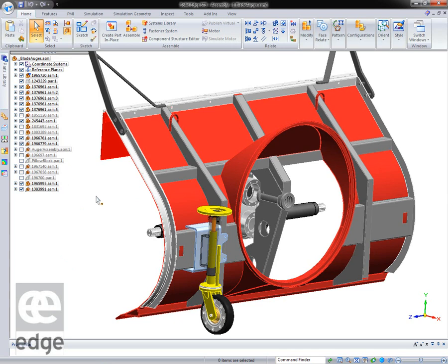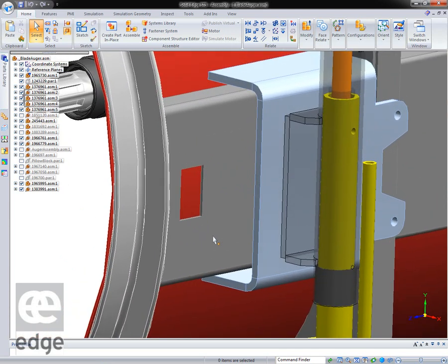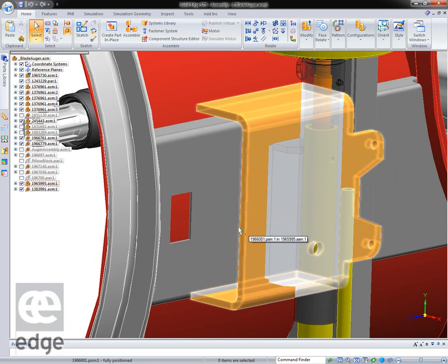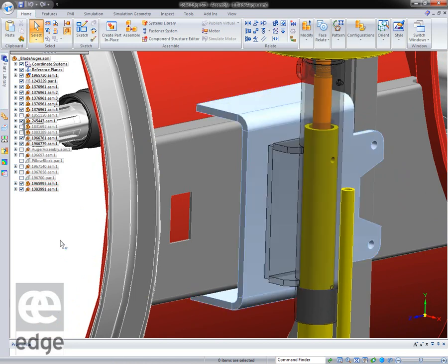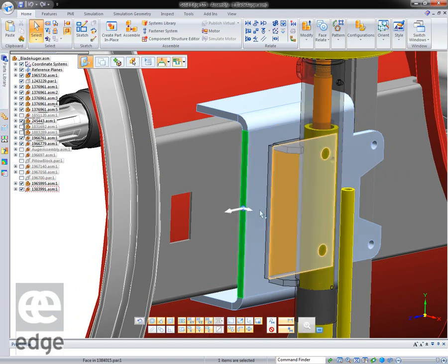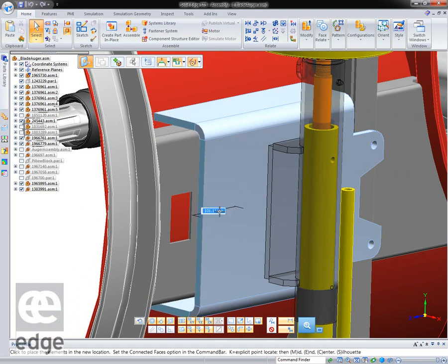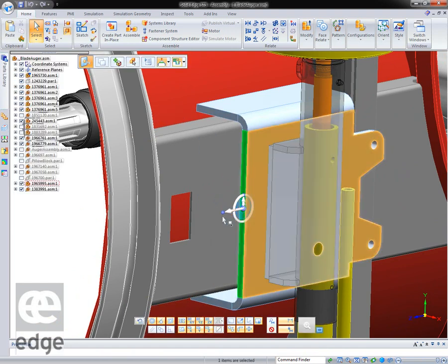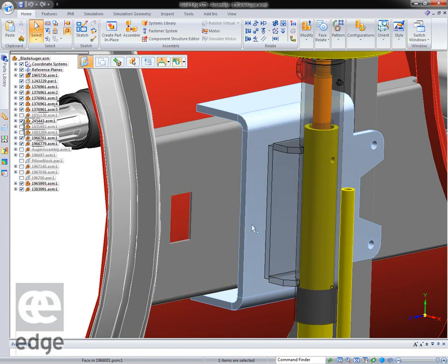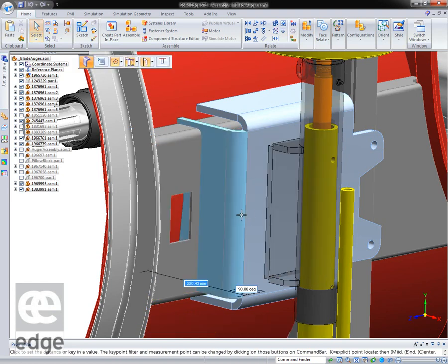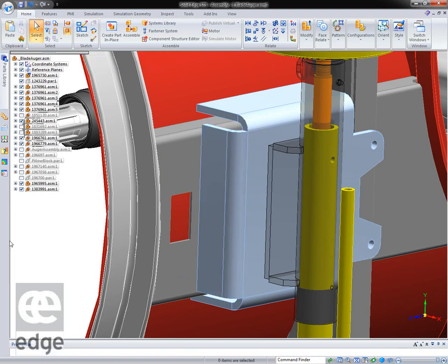So first off, we're going to focus in here on this little sheet metal object and switch to face. Select that face. You'll notice that I can extend that face, which is something I could do before, but now, let me get back to the face, sorry, I've got the flange start handle. So I'm going to build a flange on that, and I've got all my flange controls here at the bend outside, and I'll just go down to that key point just there, and that's placed a flange for me right in the top level of the assembly. I don't have to be in the edit mode.